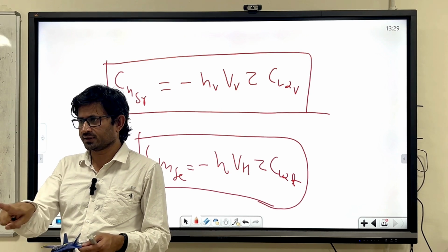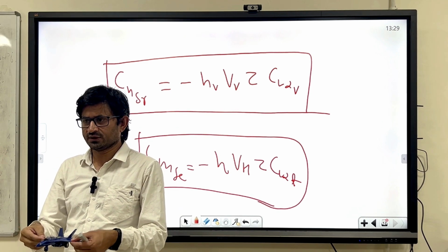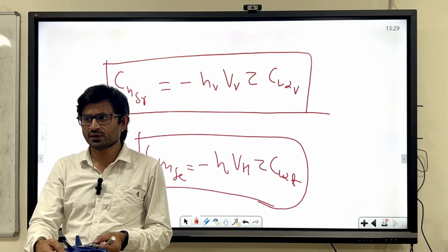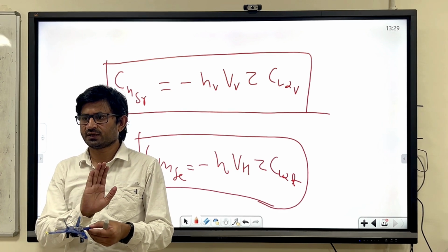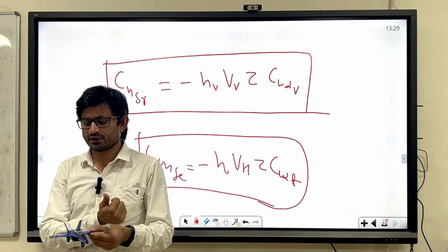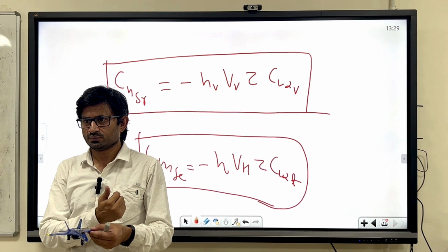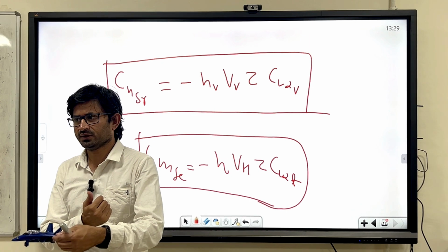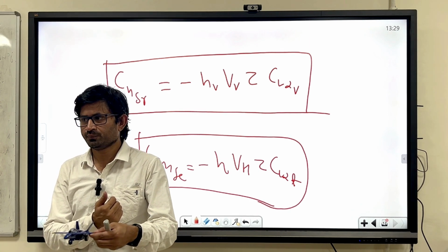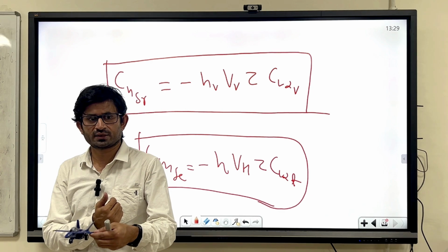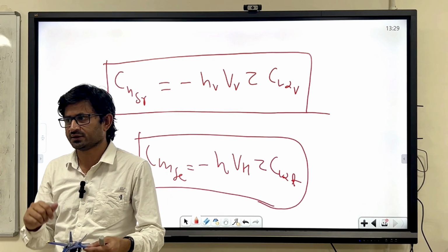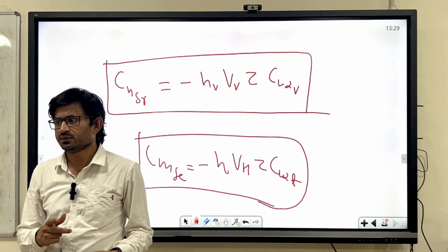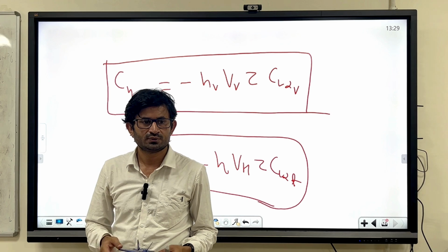Thrust is coming in this direction, right? So if this engine fails, the aircraft will try to take a yaw, so you have to counter that yaw. You have to deflect the rudder in this direction to generate the force and counter it, right? So in this case also, you are using the rudder in an asymmetric thrust condition. One engine fails, or one engine is partially working, not producing the thrust as you want, less thrust.